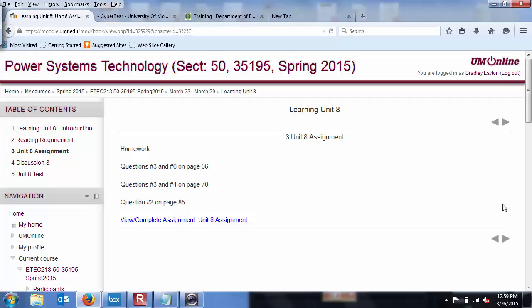Well, it's a spring. It's just a spring holding it open. The motor will not operate if the start button is pressed. In order to restart the motor after the emergency stop button has been activated, you must first reset the emergency stop button and press the start button.